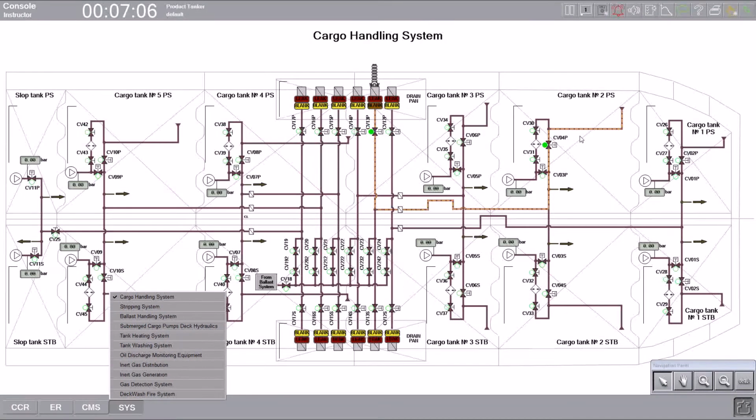So your cargo tank will be filled up faster. You have to take care about it, and during the topping off operation do not run too fast and decrease the loading rate. Okay,